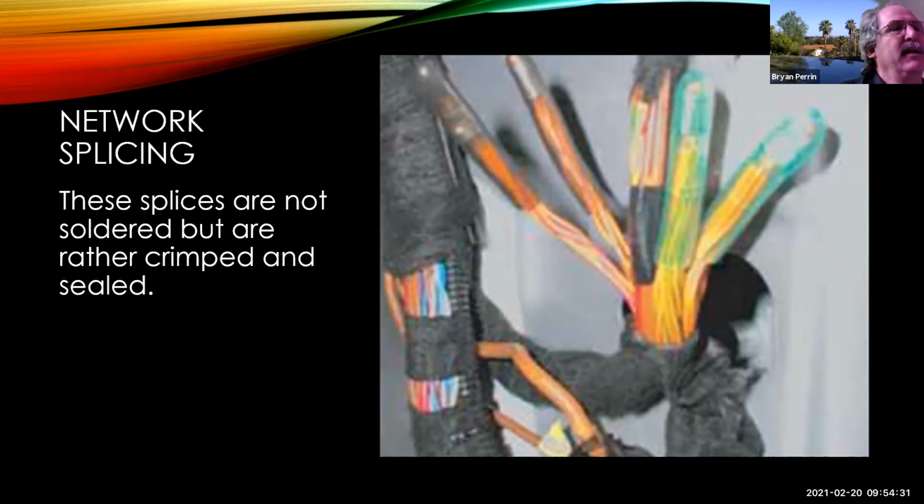And that's why I kind of leave it open to what are you good at? What are you comfortable with? I crimp a lot of stuff. Okay, it's going to depend on how many wires. Do you want to crimp and solder? I mean, the whole idea is don't put extra resistance in the circuit. So whatever you do, do it well.